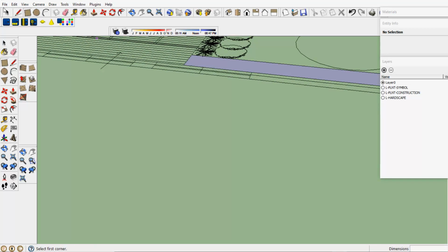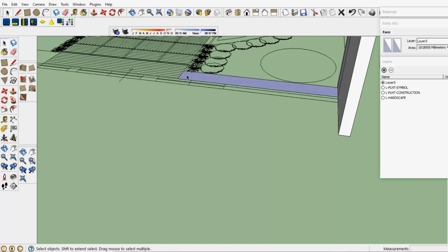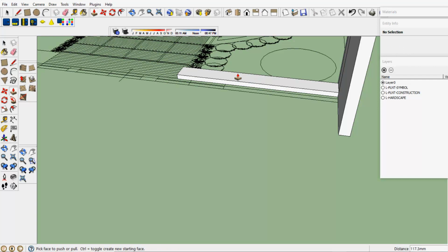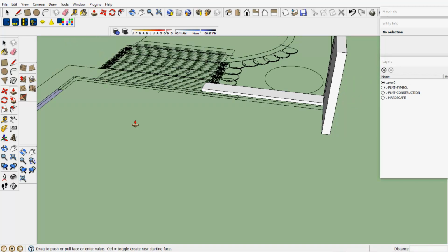So we've created, let's imagine, on a walls layer, having got those, let's select the wall that's there, and we'll use the push-pull tool, and we'll pull that one up, say 2400, and up goes the wall. The path that's out here, let's pick it and use the push-pull tool, and let's imagine we want to move that particular path up, maybe to match some decking, maybe that's going to go up 100 mils. So you can see I'm now starting to build my model.